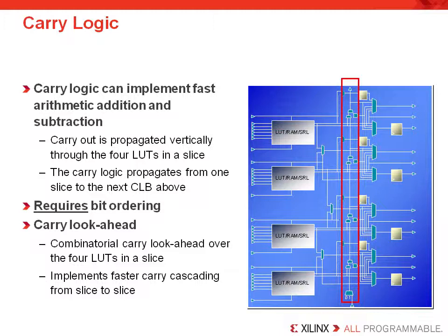This is important to note because most designs use carry logic extensively, and by using it, the least significant bit should be placed at the bottom of the carry chain. Likewise, when carry logic is used, bit ordering should be followed by the designer, with the less significant bit being placed beneath the more significant bits.